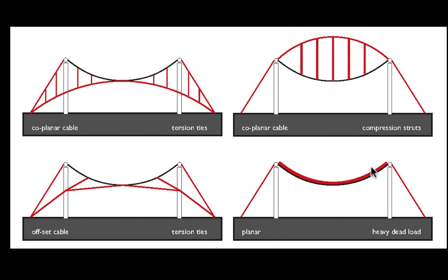We're relying on the weight of the concrete to basically pre-tension, to put the cable into tension before any external loads get put on it. And if that roof is heavy enough, we can imagine that there would be no foreseeable wind that would be strong enough to reverse the load on the cables, right? So that cable is always going to be in tension because the roof is actually going to work against the uplift that a wind spilling over the edge might give it.